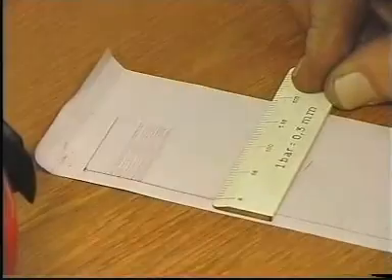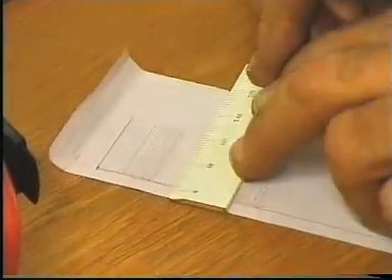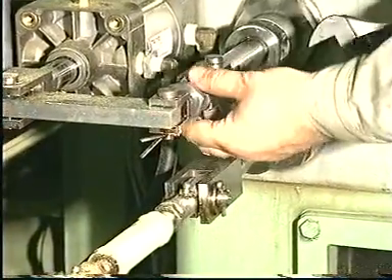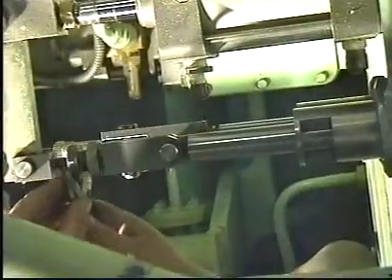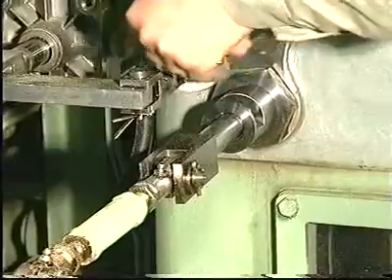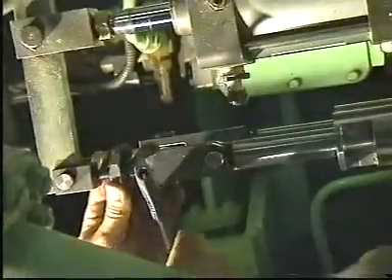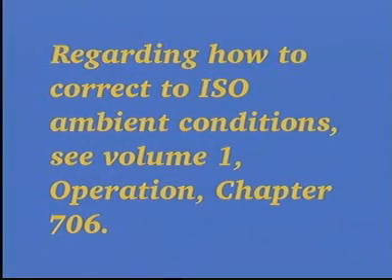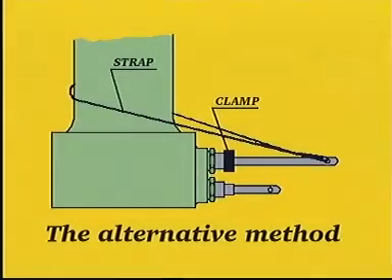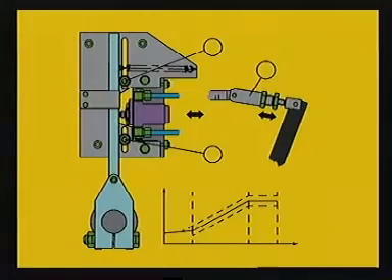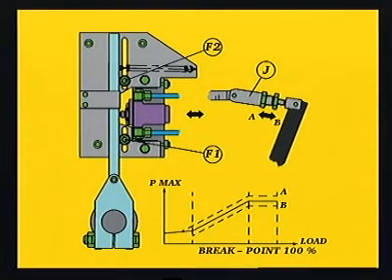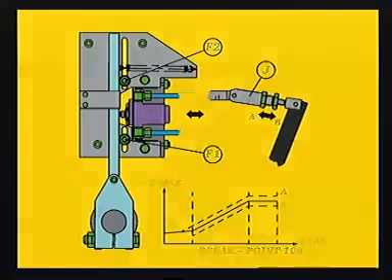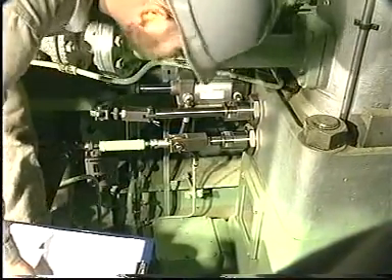Measure the maximum combustion pressures of each cylinder. Adjust the links or disconnect and lock the VIT racks so that the maximum combustion pressures, corrected to ISO ambient conditions, are uniform and have the required values. Note down the fuel pump indexes and VIT indexes.